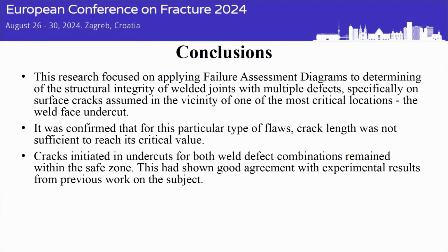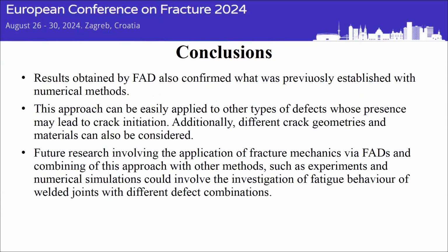And of course, this methodology can be applied, like I said, to different weld defect combinations and also to different defects. And we can also consider different types of cracks. In this case, we had an edge type crack, but you can also have penny shaped cracks, surface cracks, or there are a lot of different options that can be explored.